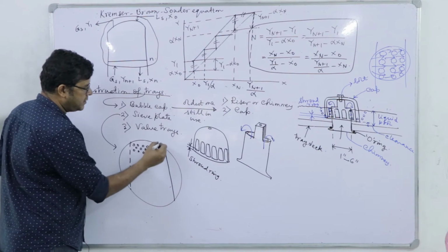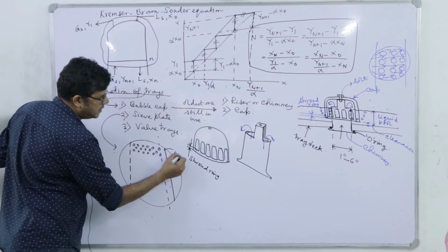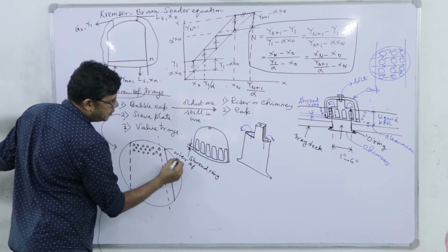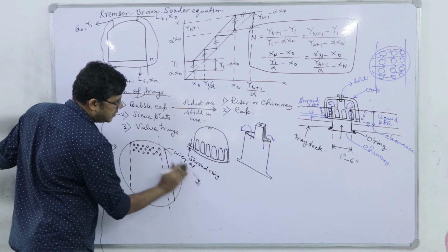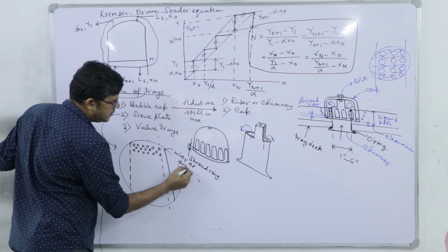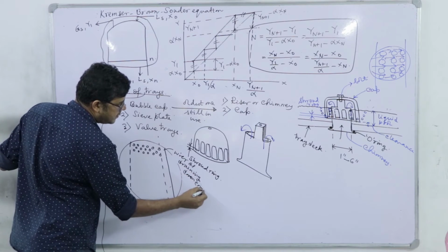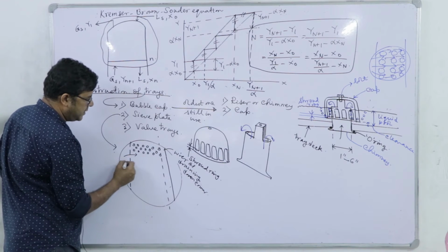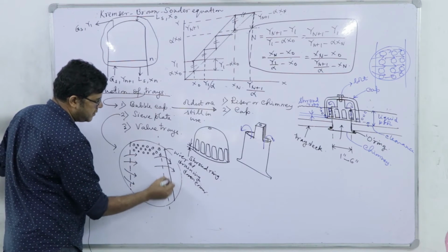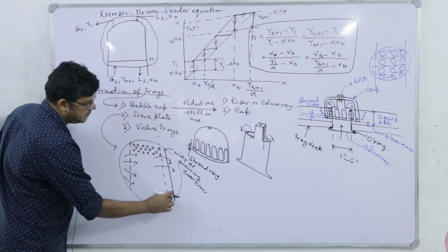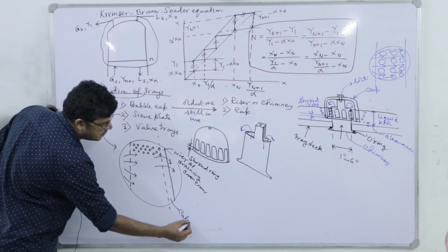Like this, right? And here you see this is the weir of the outgoing or draining downcomer. The liquid flows from this side and goes here, and over this region, right, we have no sieves, and this is called the calming zone.